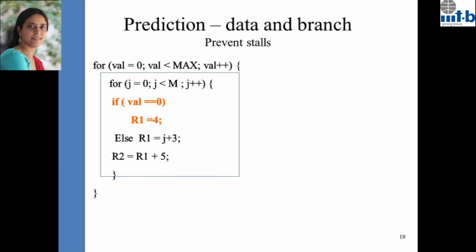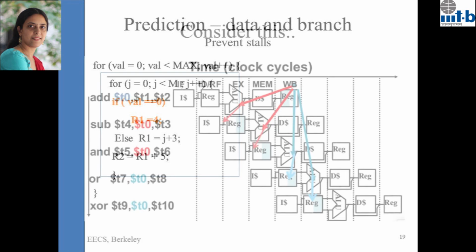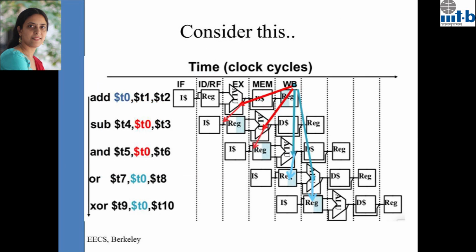So it again depends on the data dependencies, like I said. I have, let's say, this set of instructions. Which instruction has to come depends on the dependency. Unless the processor looks at these instructions, it does not know which one to schedule first. So the control unit will look at these, and if there is anything which does not have dependencies, it will move it ahead. That is the out of order execution engine, which looks at the instructions and schedules them ahead of the other ones.